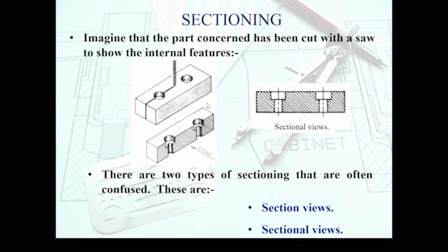You will hardly have anything which doesn't have any details concealed within an object. So in 95% of the technical drawings you'll see, there will be a sectional view going through it to reveal the insides. Okay, so once again, what we assume here is this particular part, which is not possible to dimension fully without opening it up, and we just pretend that we are going to cut it out. So we create a cutting plane there, and then we show the insides of that like so. So we can say this is the front sectional view or sectional front view, etc. And this then allows us to dimension these diameters here, these heights, and this diameter here without breaking any rules.